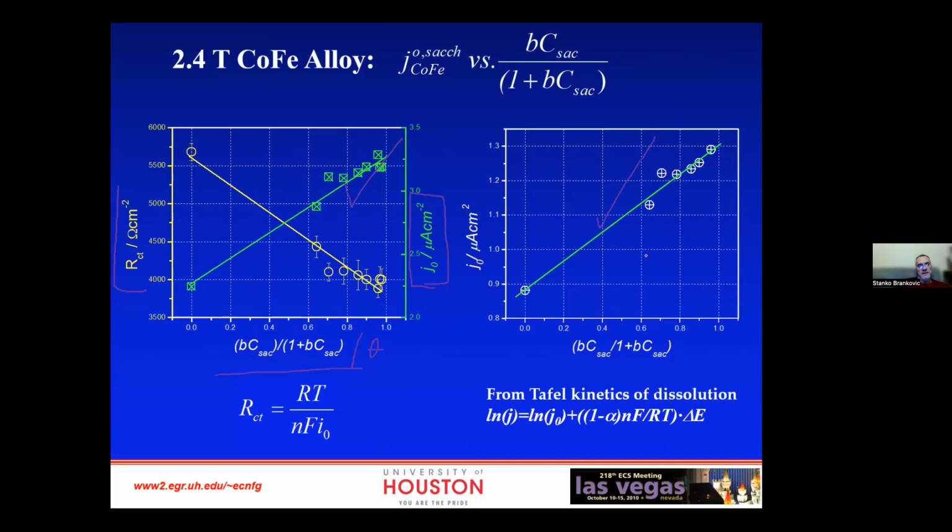So it seems like that when we do electrodeposition with additives, they do incorporate and they do affect the alloy's ability to resist the anodic dissolution. More incorporation of the additives, which is proportional to the coverage of the additives, is likely to cause poorer resistance to the dissolution, basically. And you can see the charge transfer resistance drops or exchange current density increases.